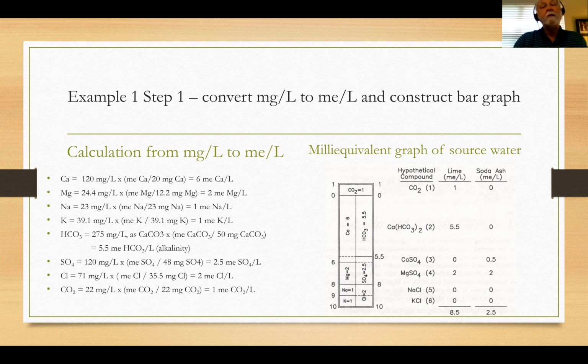When I add the lime, I precipitate magnesium, go to magnesium hydroxide, but the problem is I've got calcium carbonate that is formed, or calcium sulfate, and I have to add 2 milliequivalents of soda ash, just like I did in the line above, to convert it to calcium carbonate. Again, sodium chloride, potassium chloride, not divalent, they're monovalent, +1 ions, don't contribute to hardness, don't have to soften them.